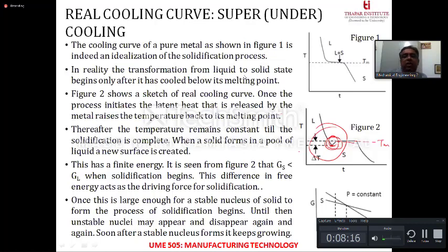Now, this process takes a long time in homogeneous solidification. Although the grains are very good and very fine and the stresses are not high as compared to heterogeneous solidification, the process takes a longer time. So this type of curve that you see over here reduces the time taken for the solidification process to initiate. As a result, what you observe is rapid solidification.